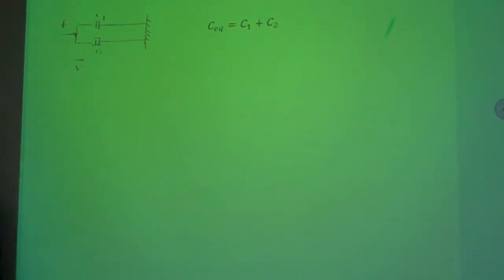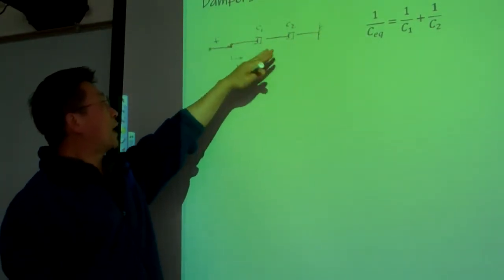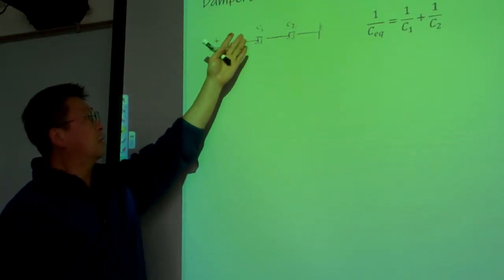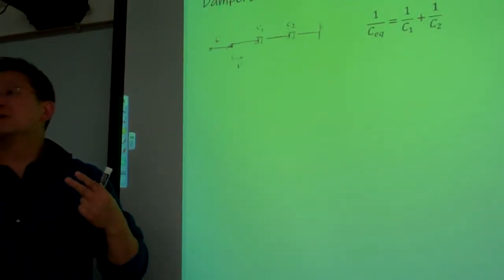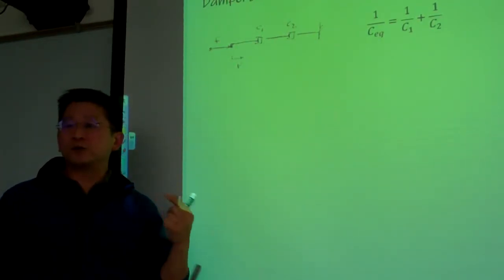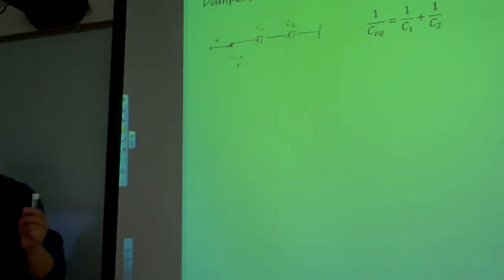That is the tip I shared with you for the spring. And if that connection is in serial, then the force in each component must be the same. We simply use the two tips to tell; when the configuration is more complicated, we stick with the two conditions to justify whether that connection is parallel or serial.